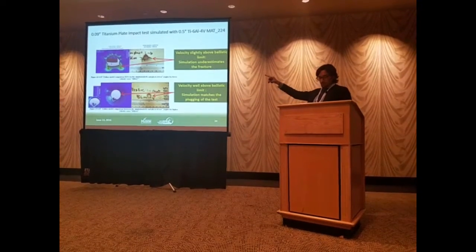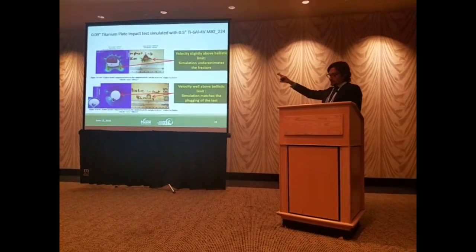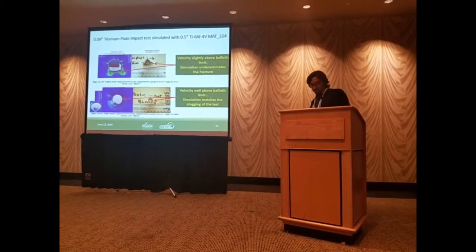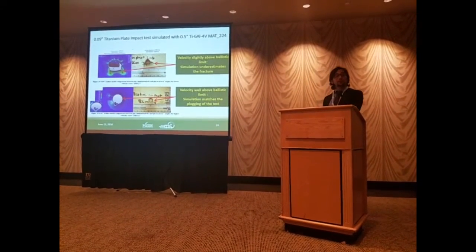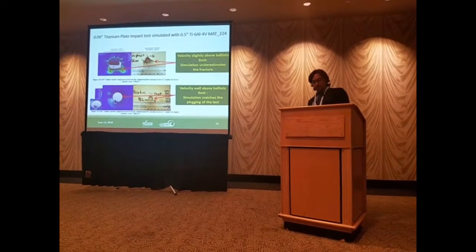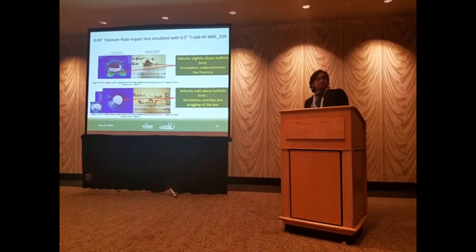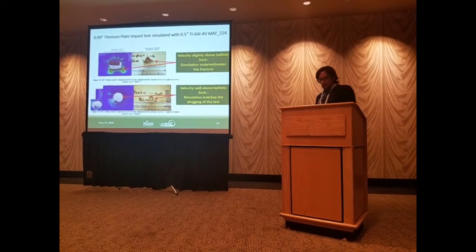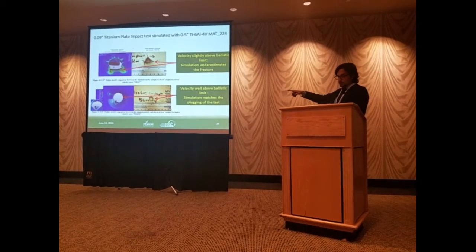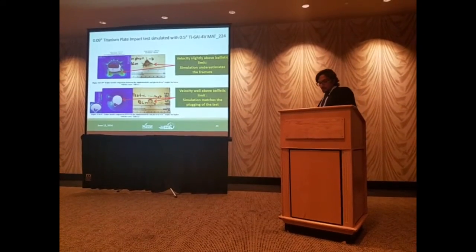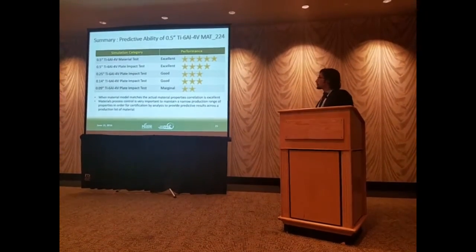You should note that the test and the simulation shown have two different initial velocities, because we wanted to compare the fracture mode for a contained case, and using the same velocity it wasn't possible. So instead, at high velocity, we have the same straight plug shape.